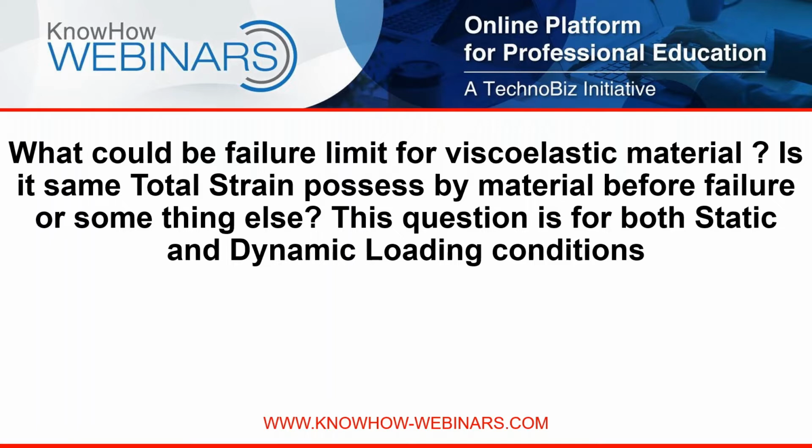Now, based upon your service conditions, you have to make a judgment: 500 Newton decreases to 300 Newton, whether this stiffness is good enough or not. Generally, a decrease in stiffness of 20% or more is not good. So that would be considered a failure. So this is how you demarcate both the conditions and you come up with your failure criteria. That would be my answer for question number 7.